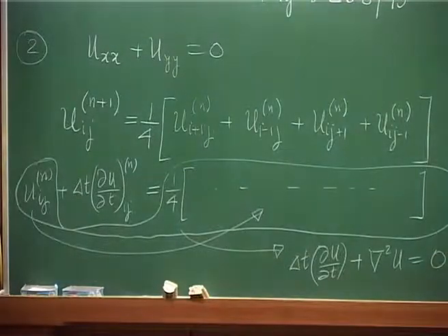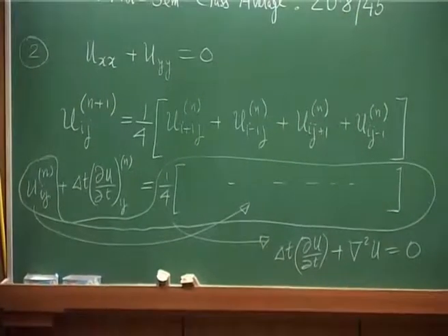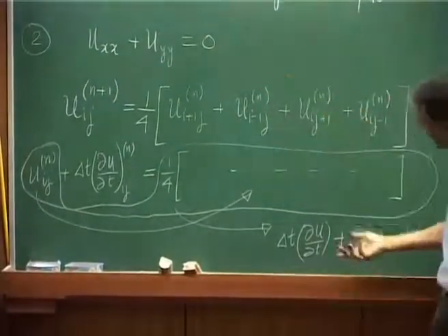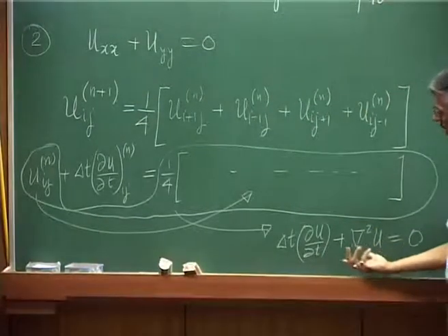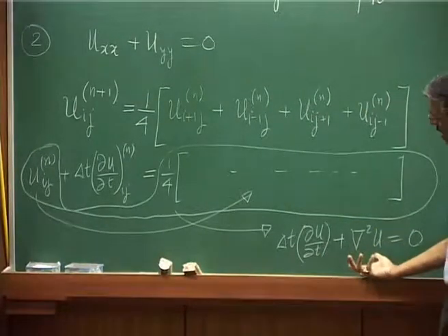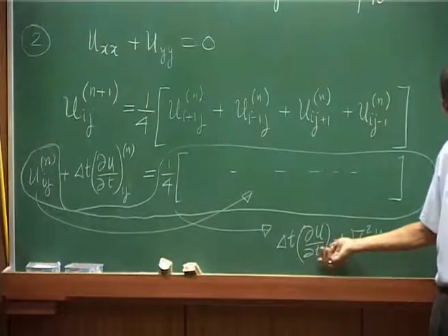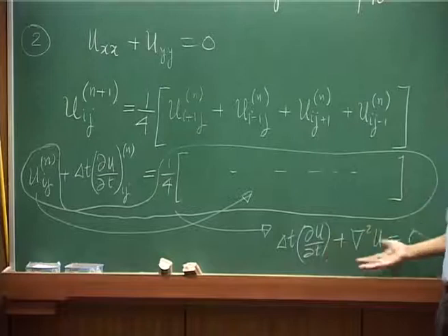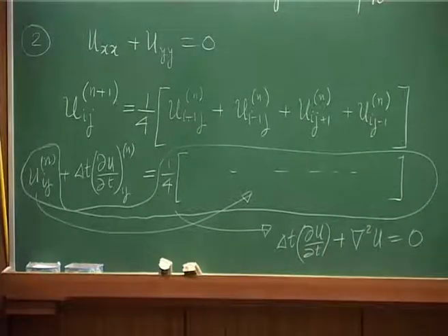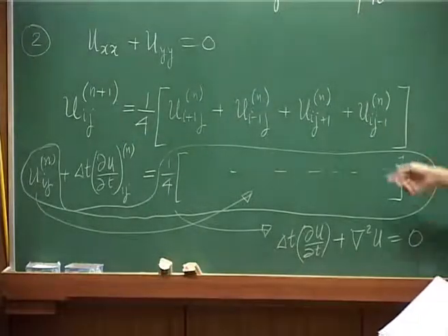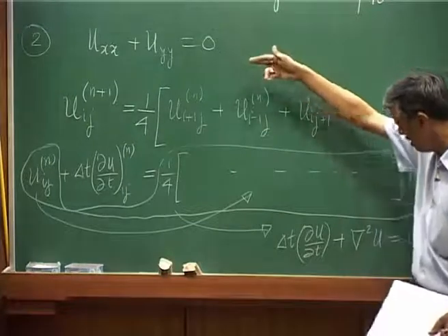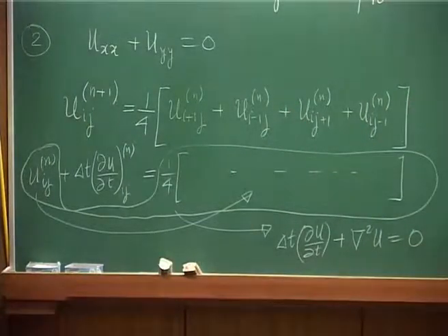Say something like this. Okay. The whole idea is that when you actually try to solve an equation of this kind, you convert it into a pseudo time dependent equation like this, and you are interested in the steady state when this term drops out. When del u del t is 0, then you get back to your original equation that you set out to do. So, now this part is easy, right. So, you could get the equivalent equation. So, we tried to solve this equation, but in effect we are solving an equation of this kind.